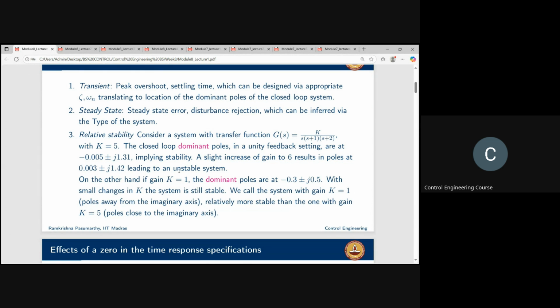What I am saying is, for the closed loop system, you will want to have two poles much closer to the origin than the third. Got it? But still, much closer. I mean, a pole being five times or 10 times closer or far away is pretty much a thumb rule. There is no specific number. The more far away it is, the more accurate your design specification will be satisfied.